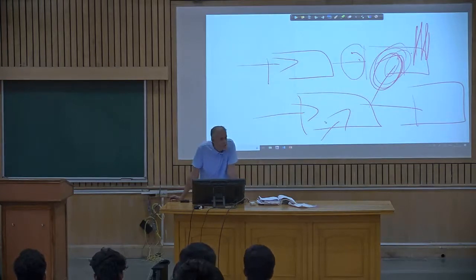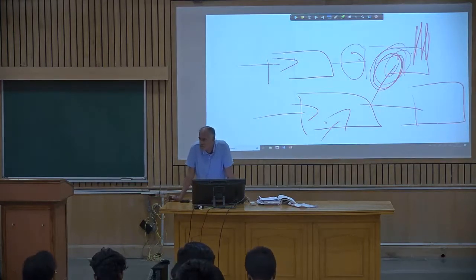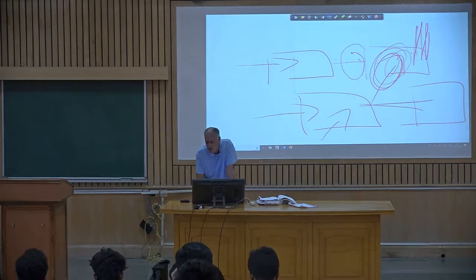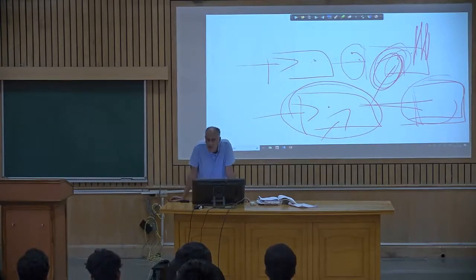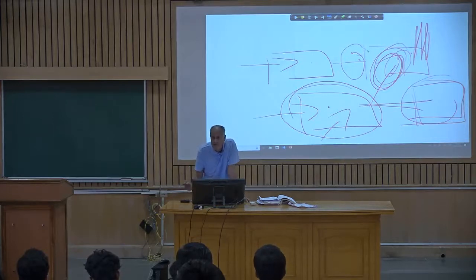They're initially mixed, and whatever else happens there, maybe a chemical reaction happens or some just physical mixing happens, and then they come out here, and then you have the total energy. So you write energy balance for both A and B here, and then depending on what process happens here, you write the energy balance when they exit. Here it's only for A, and then when the material is out, then it mixes with material B.